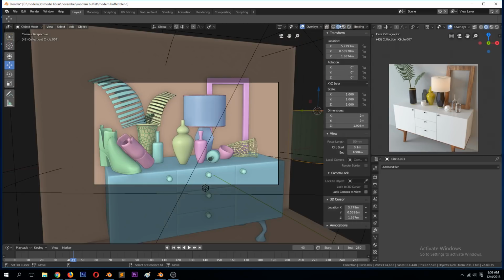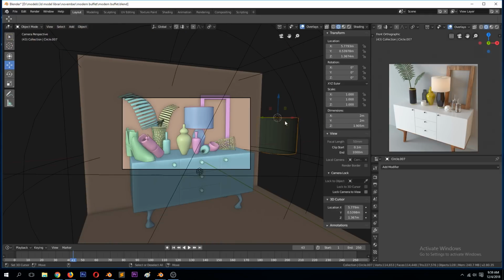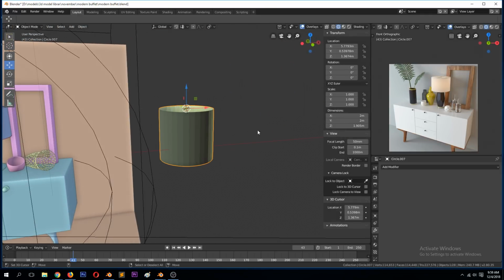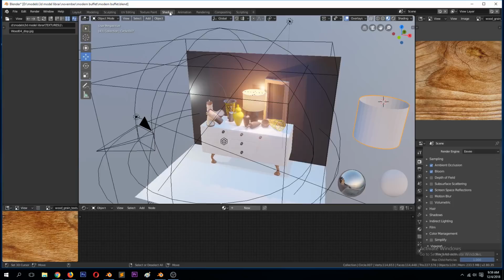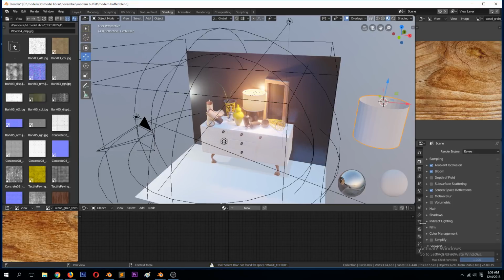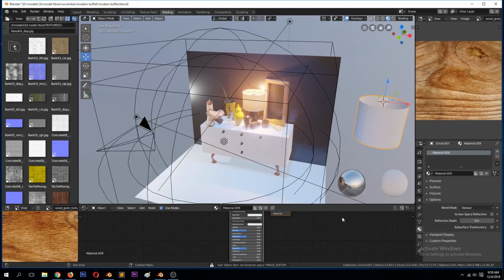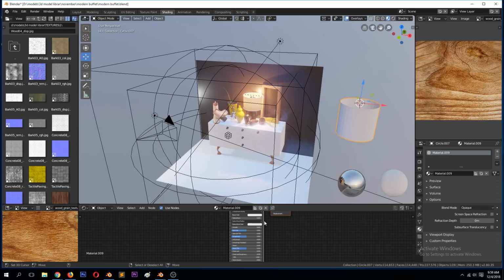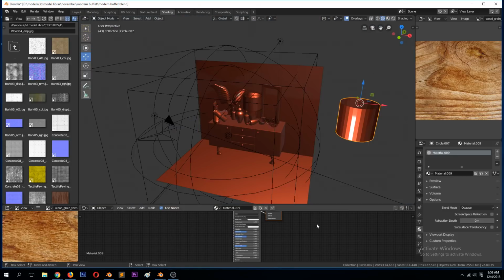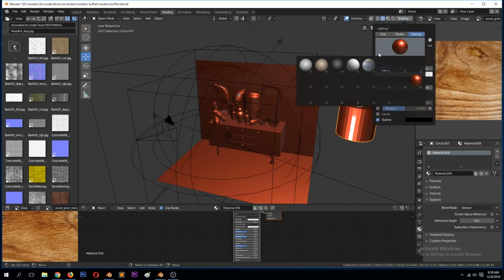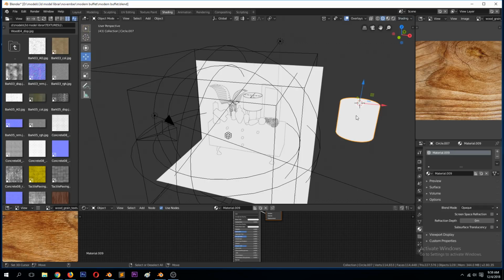Just go into this workbench preview, and then apply the materials directly there. So maybe we can go to the shading first and add the material. We know that Blender crashes when we change the material here, so we can just go back to workbench. Let me make sure that I'm not in flat mode.